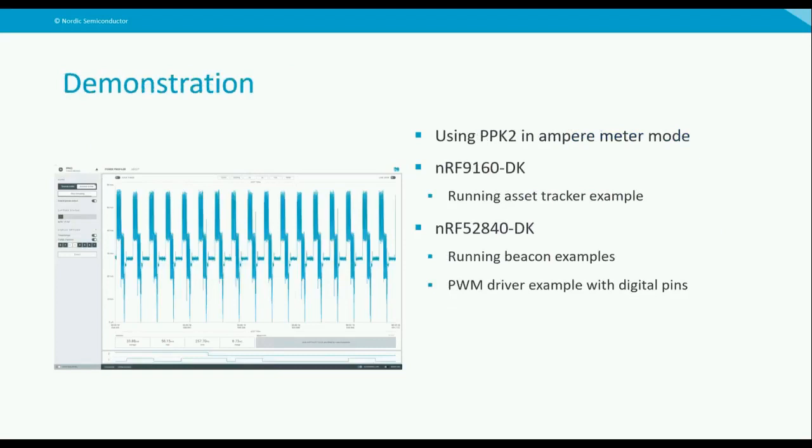Alright, I will now show you a demonstration of the PPK2. For this demonstration, I will first show you the PPK2 software in general, using an nRF9160 DK that is running the out-of-the-box asset tracker example. Then I will use an nRF52840 DK with some different examples, showing how some minor mistakes in your code will impact your power consumption. I will also show you a practical usage of the logic port.